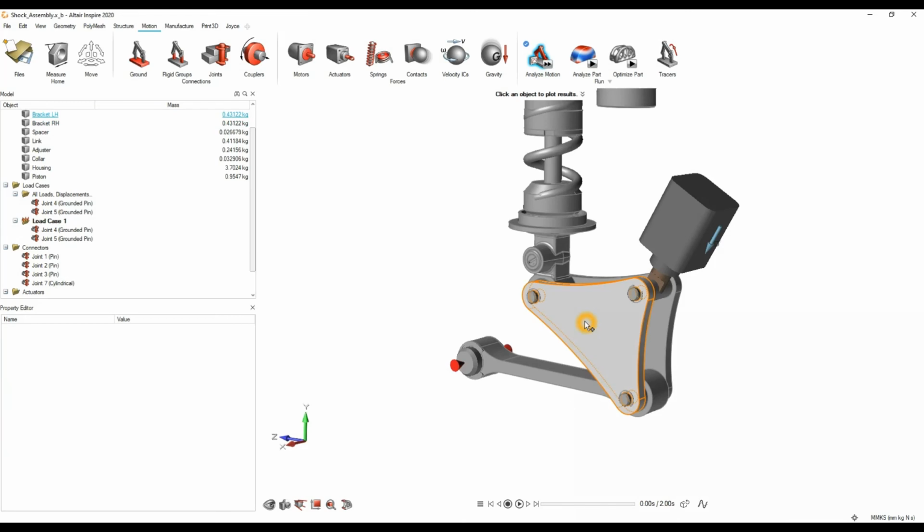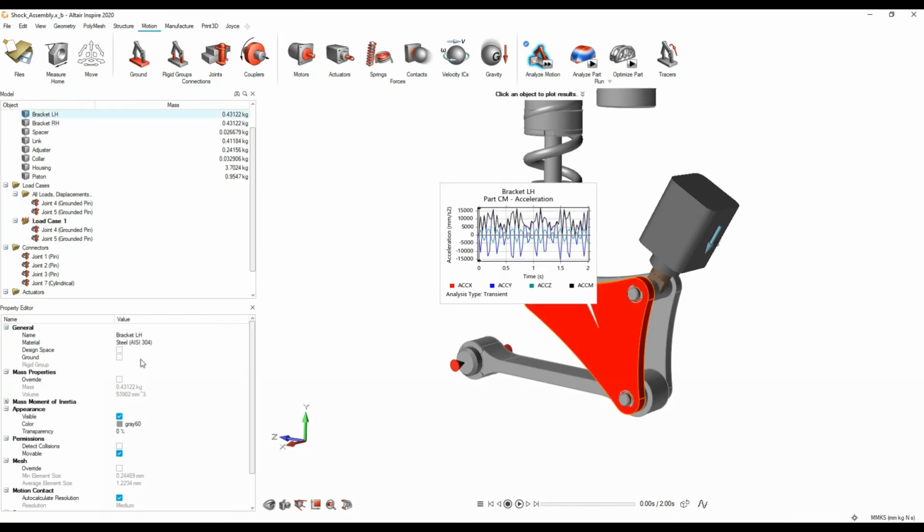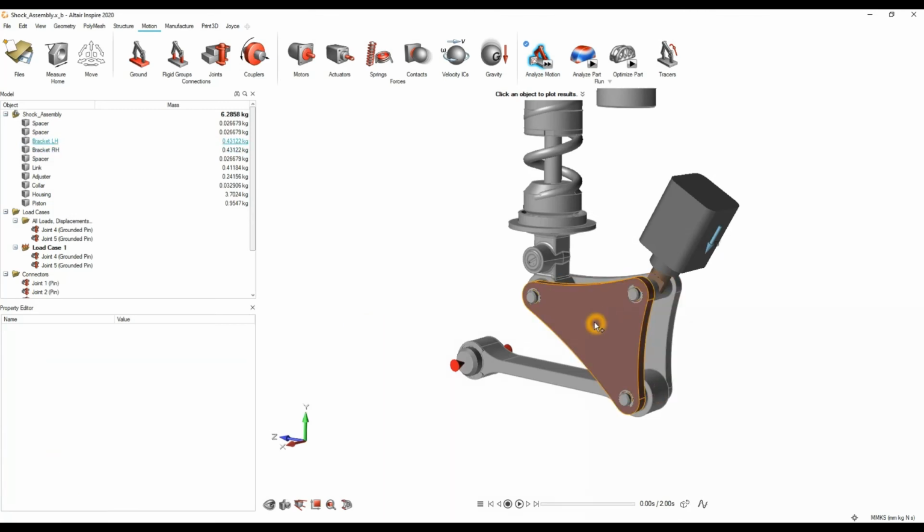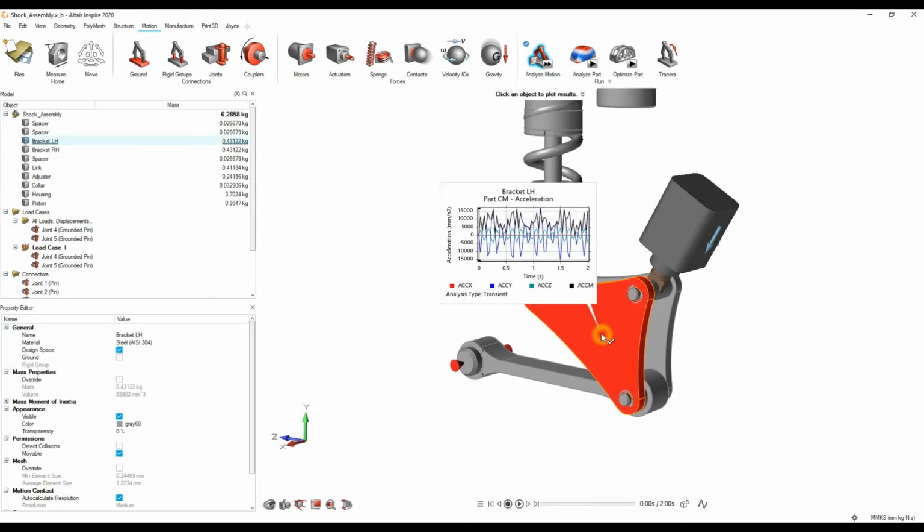So if you want to take it through for an optimization, you can simply go to where the part is in itself, and obviously where it says design space, if we want to tick it, you'll see that that turns the part itself from a grey colour to a burgundy maroon colour. And what that means is we're telling the optimizer itself, the solver, to implement the optimization on this part, and it can take away any material that it likes from it.